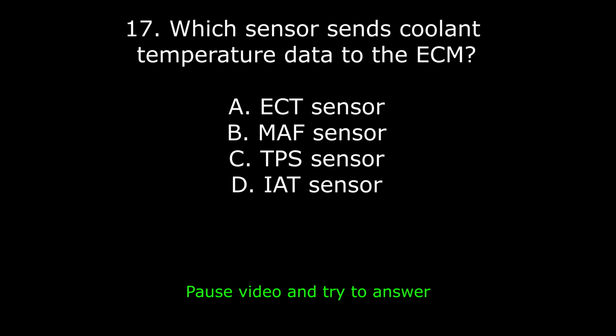20. A vehicle's temperature gauge reads high, but engine isn't overheating. Likely cause: A. Faulty gauge circuit. B. Blown head gasket. C. Weak radiator cap. D. Low oil pressure. Answer: A. Faulty gauge circuit. A shorted sender wire or gauge fault can give false high readings.